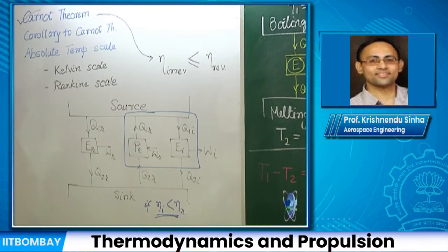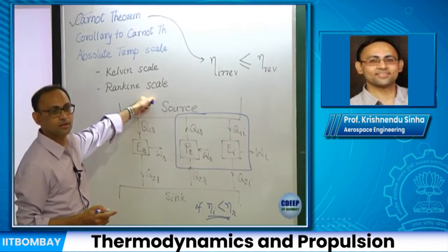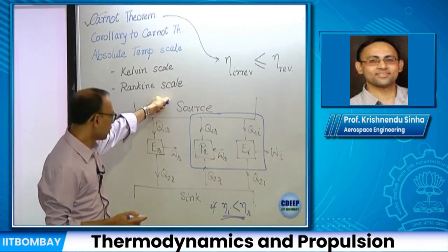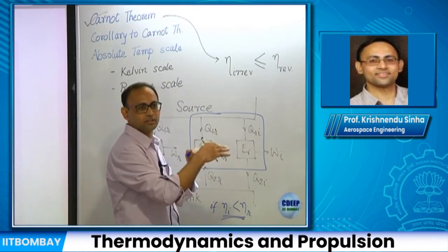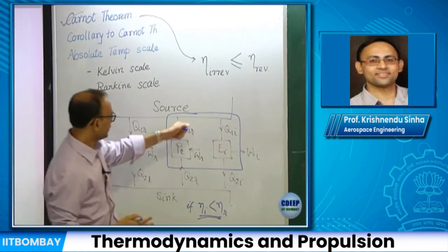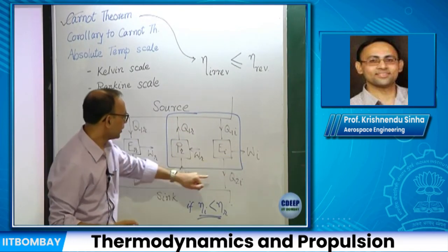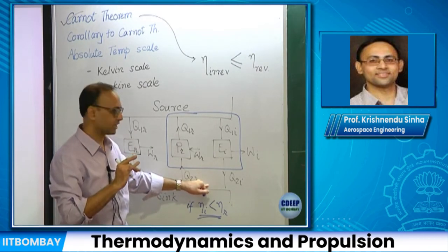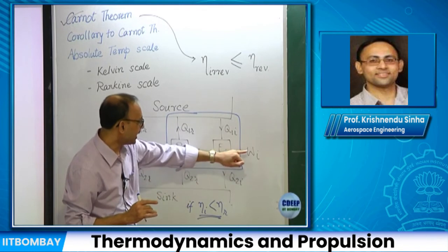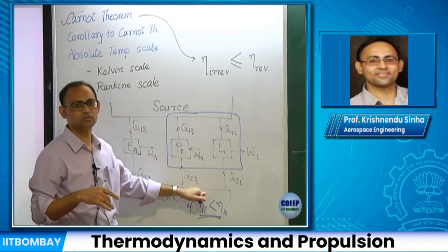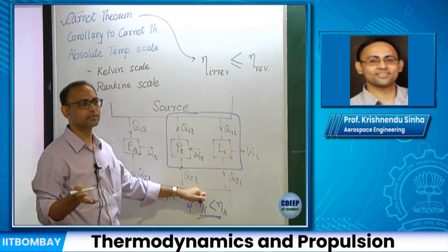We'll get net heat input and we'll get net heat output. We can still eliminate the source. Yeah. So all of these things will become opposite, right? So if we do that, the argument we have to do is all of these will become opposite. In this case, we had a net work output while we got the same amount of heat coming in from a single source, and we said that violates second law. If we start with the opposite argument, we'll get a net work input, an equal amount of heat going back to this source. And does that contradict second law?